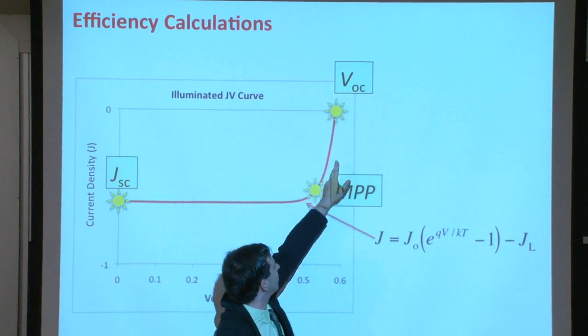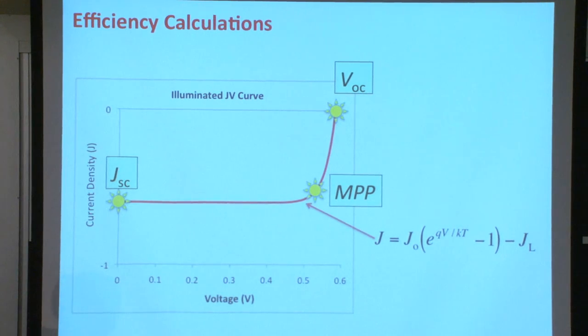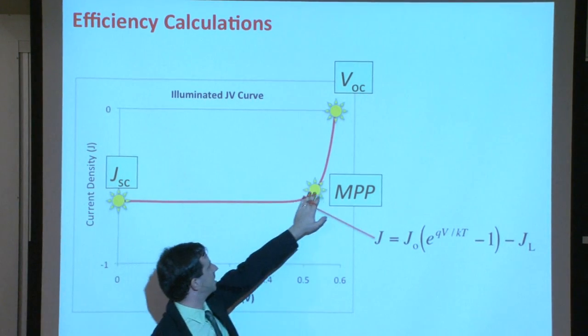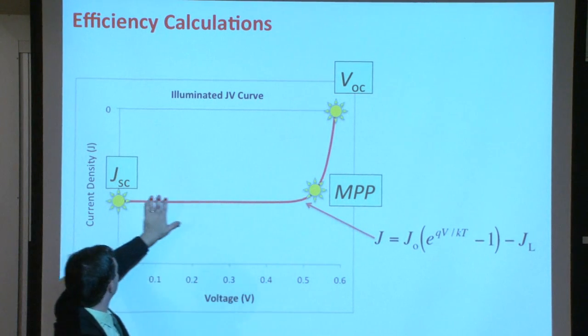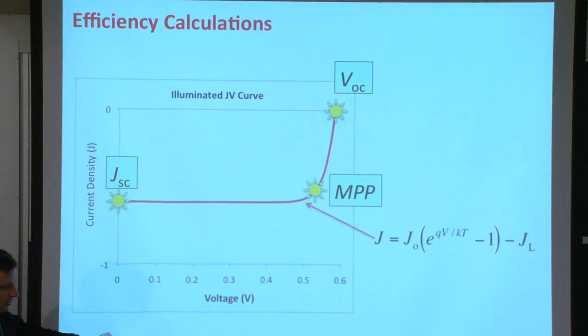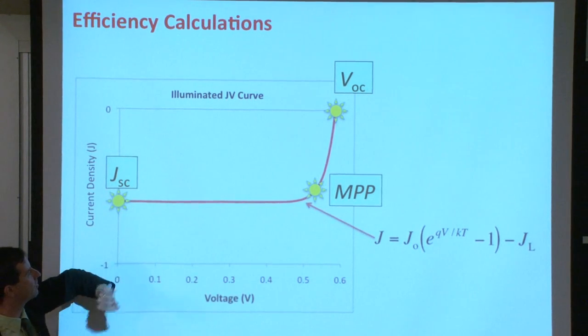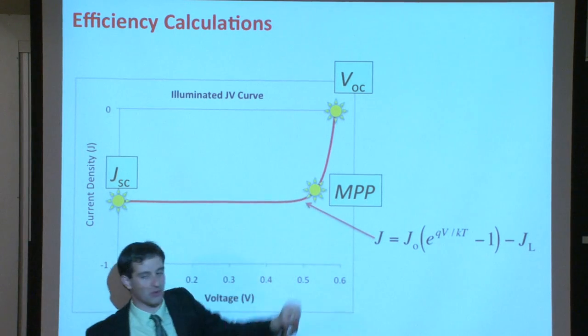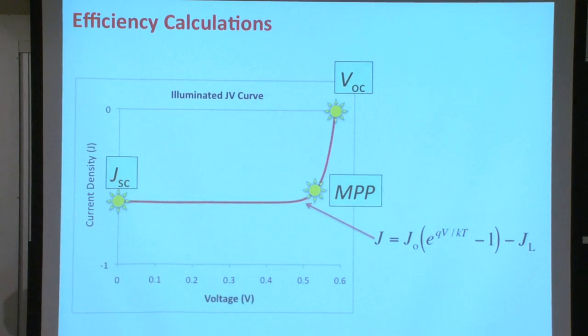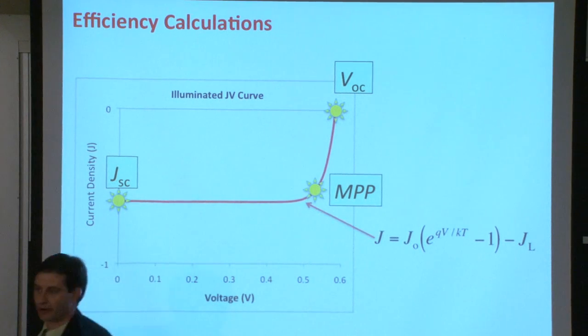Open circuit. And voltage, because it's an interesting point: it's the maximum voltage, represented here in the fourth quadrant. And somewhere in between the point of open circuit voltage and short circuit current, again, because you're short-circuiting your device, current is flowing through, but there's no external load, there's no power being deposited on an external load. Somewhere between these two extreme conditions where there's no power flowing through the external circuit, you have a maximum power point where there is power being deposited across your external circuit and a lot of it, right? That's the maximum power point. This is a point at which the solar cell is producing the maximum amount of power output.